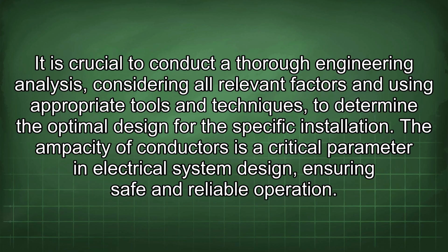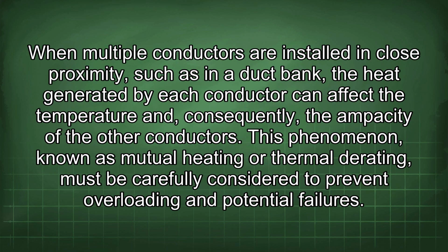The ampacity of conductors is a critical parameter in electrical system design, ensuring safe and reliable operation. When multiple conductors are installed in close proximity, such as in a duct bank, the heat generated by each conductor can affect the temperature and, consequently, the ampacity of the other conductors. This phenomenon, known as mutual heating, must be carefully considered to prevent overloading and potential failures.